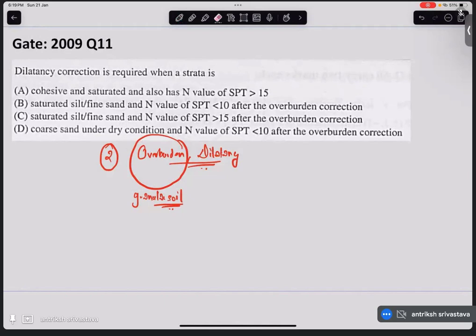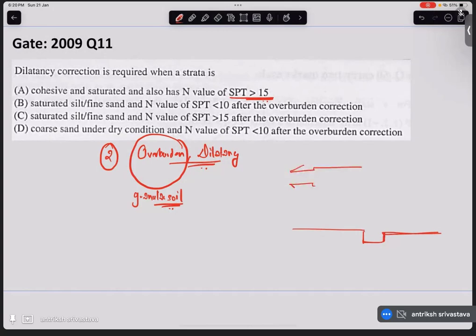What is SPT? SPT, standard penetration test. We do this test to explore the vertical variation of the different kinds of soils that we have in a particular area. Let's say that this is our ground. We dig a small hole, and then we put in a split spoon. Basically, the cross section looks like this. This is the point which faces down, and these are the sharp edges that penetrate the soil, and your sample of soil gets stored in this place.